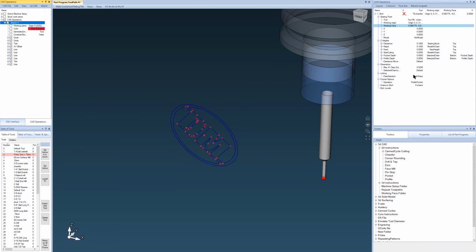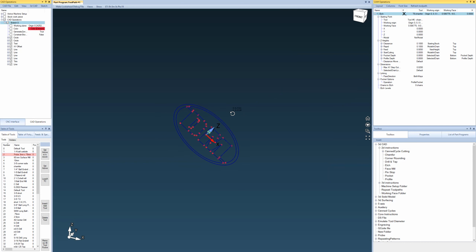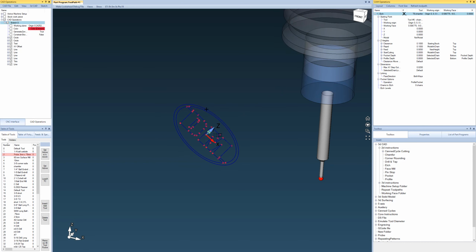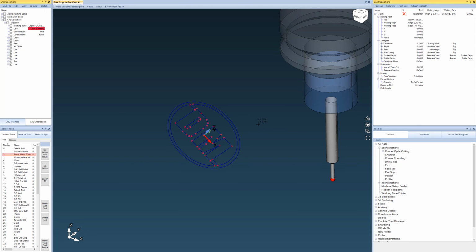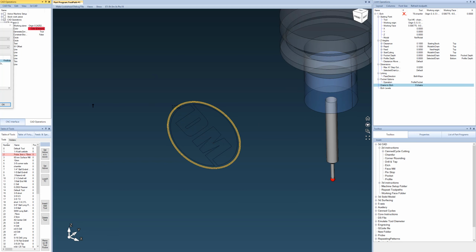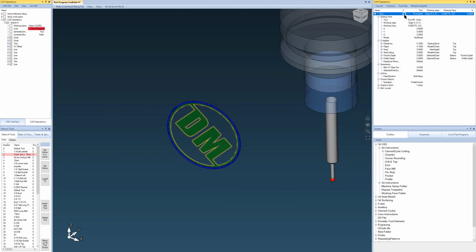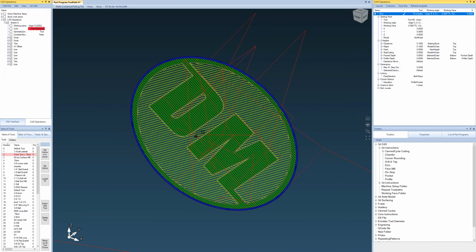Now I close this down, and if I hover over the working face, you can see that it populates the values there, so you can see it did something. If I click on the etch, you can see it did exactly what we wanted. It put the working face in the center of our sketch, just like our actual sketch over here. Now we can fill out the etch just how we normally would with any 2D sketch. We'll hit change to machine, click on the outside here, and then tell it to recompile, and then we get something like that.